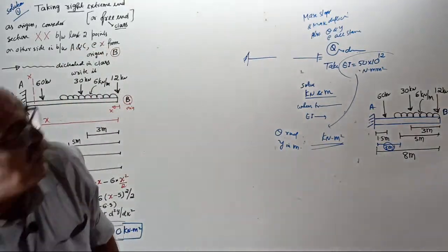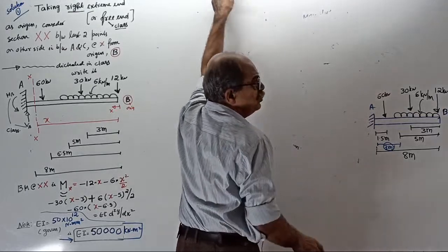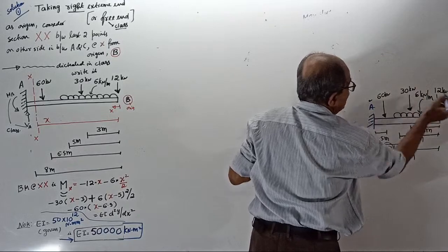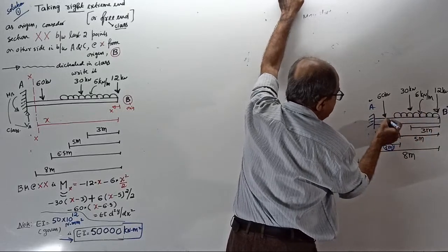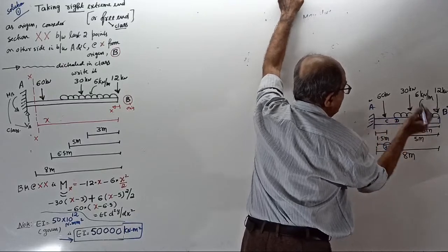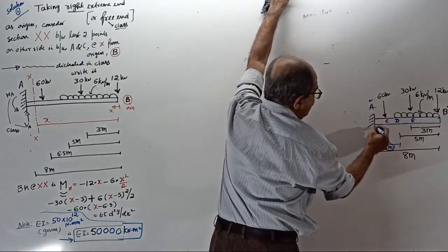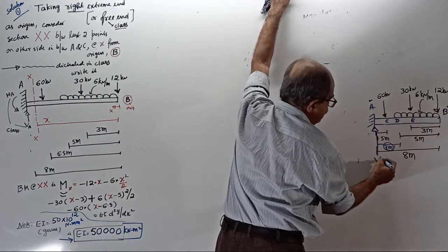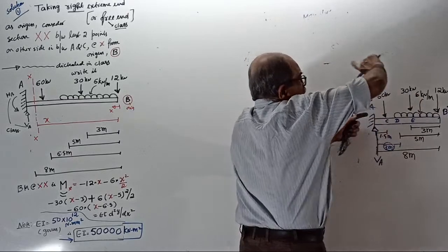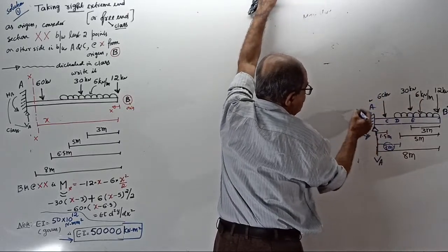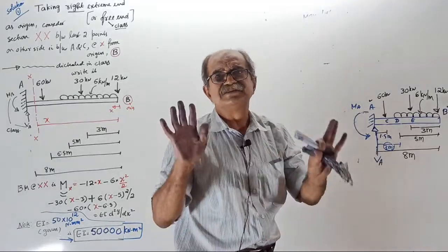Yes, okay. Now see the question there. Decide which is the better origin. Actually, you can take either A origin or B origin. Name the points A, B; I will call this point C, this point D, this point E. Write one more thing: loads are acting down, so there will be a vertical reaction here, up. And this load will rotate the beam clockwise, so there will be a balancing anti-clockwise reaction MA here. Even if you are not finding the reactions, make a note that reactions are there.